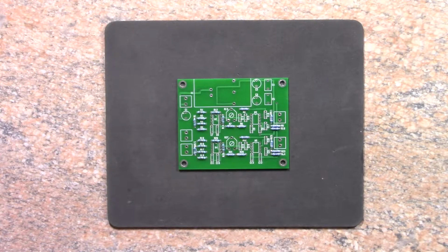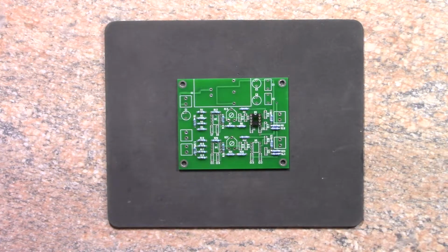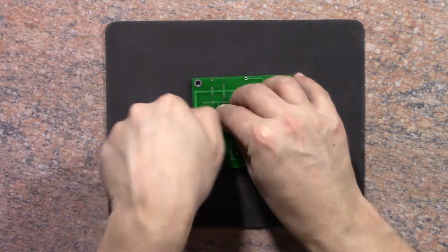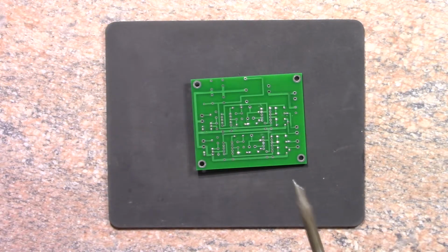So at this point I've soldered in all the resistors, and the next level up would be the ICs or integrated circuits. Now instead of soldering them directly to the board, I prefer to use an IC holder or IC socket. So you solder the IC socket into the board and then you push the IC into the socket. So if the IC ever fails, you can simply plug it out and plug a new one in without doing any soldering. And in a similar way, you take the IC socket, turn the board upside down, push it firmly against the mat, and then simply solder it onto the board.